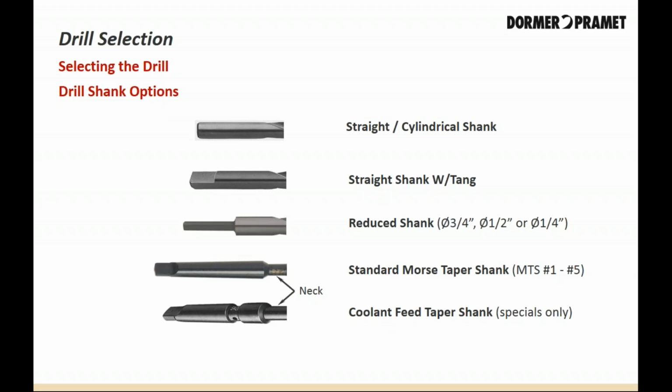Common shanks are also straight shank drills, but common shanks are used more on solid carbide drills and high performance drills, where the idea is to greatly reduce the number of collets an end user has to stock. Usually an entire range of drills from 3 millimeters up to 20 millimeters. Cutting diameters range can be up to 150 and over individual sizes. Those can all be held in only 8 collet sizes: 6 millimeter, 8 millimeter, 10 millimeter, 12, 14, 16, 18, and 20 millimeter collets.